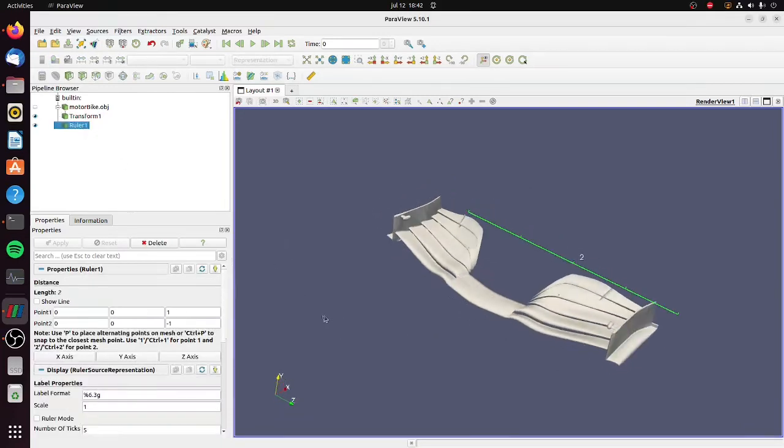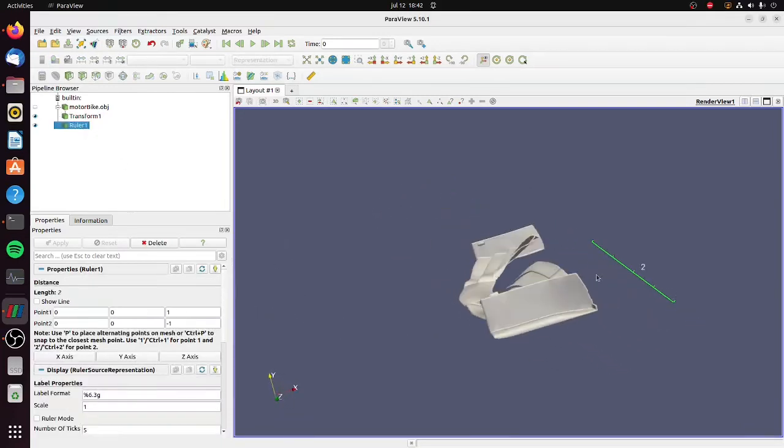Okay, so now we see that the front wing is shifted forwards. If you're wondering why this is, I believe it's because Formula 1 will simulate from the front axle as the 0 point. So everything in front of the front axle is negative, and everything behind the front axle is positive. So that's why it's negative. So let's first find the front point of our simulation, and I already happen to know a good value, so we're going to set our x value equal to -1.5.